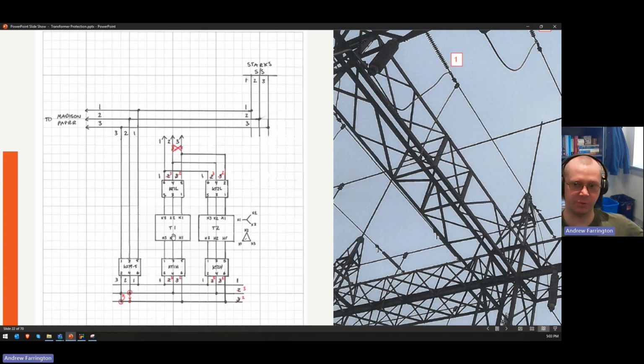And then we traced it through to the H1, H2, and H3 bushings of the transformers and found that, yes, in fact, there were two swapped phases, and they were all DY1 transformers, so the 34 kV was 60 degrees out of phase, and thus the reason they couldn't use that switch. So we added that to the list of things to fix during this outage.